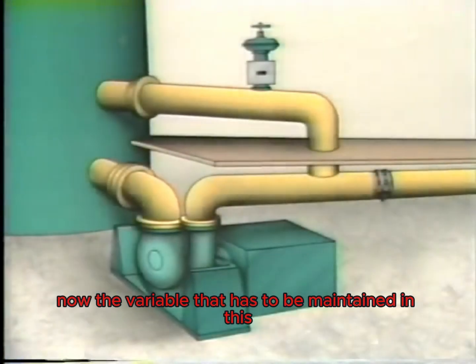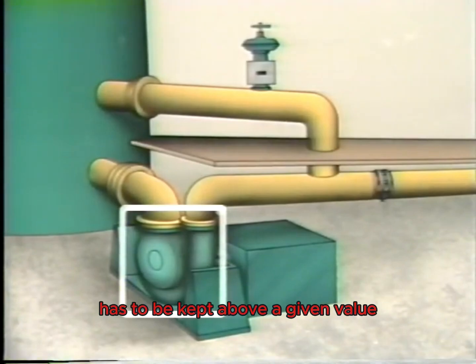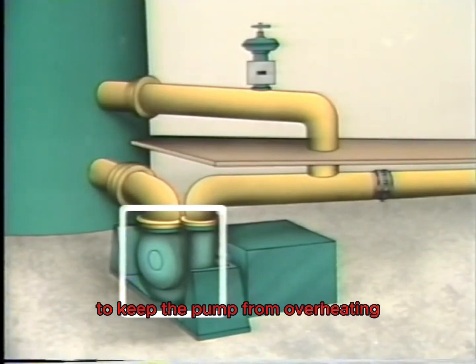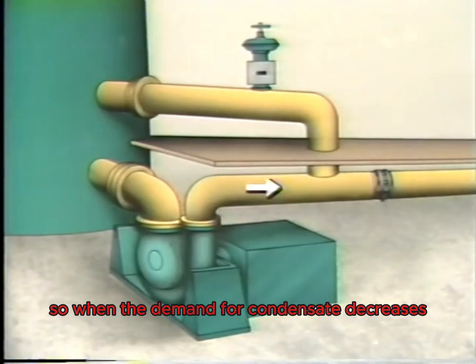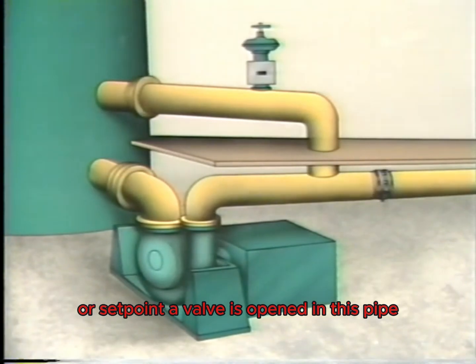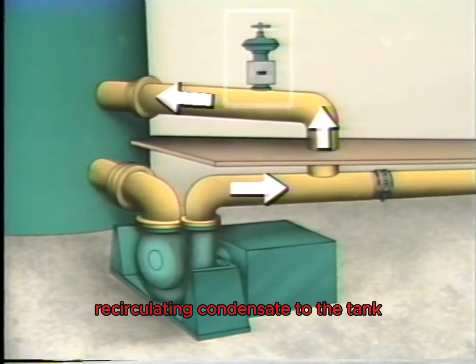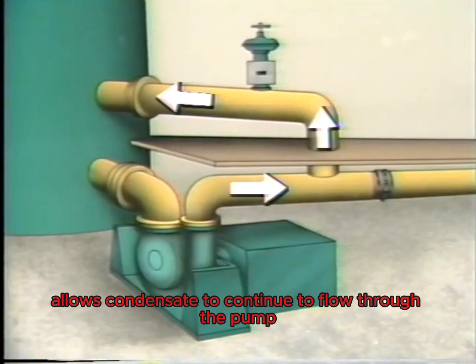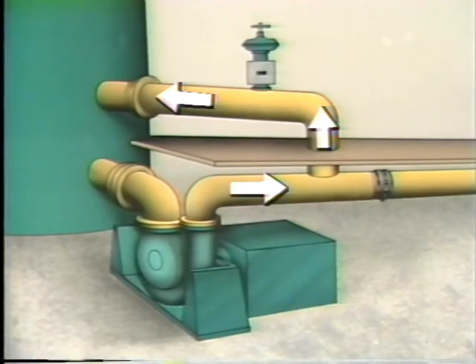Now, the variable that has to be maintained in this process is flow through the pump. Flow through the pump has to be kept above a given value to keep the pump from overheating. So when the demand for condensate decreases, causing the flow to drop below the given value or set point, a valve is opened in this pipe to recirculate the condensate back to the tank. Recirculating condensate to the tank allows condensate to continue to flow through the pump at some value above set point and prevents the pump from overheating.